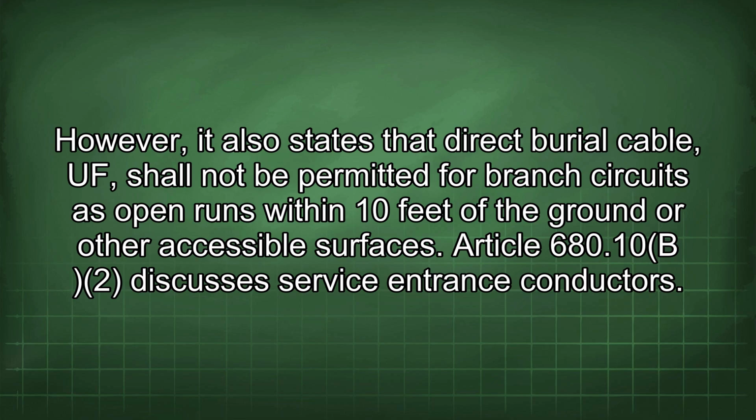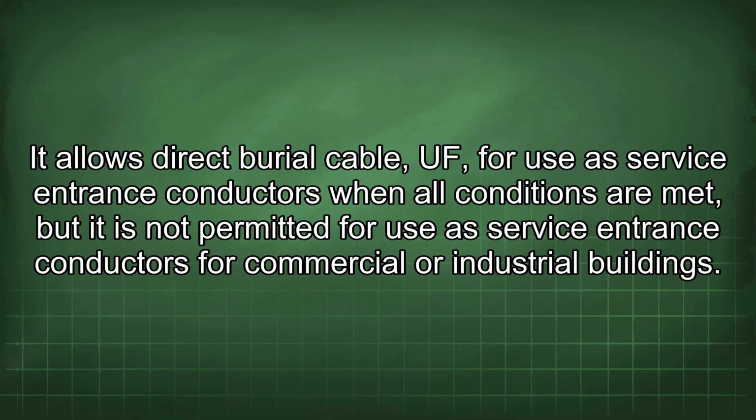Article 680.10(B)(2) discusses service entrance conductors. It allows direct burial cable (UF) for use as service entrance conductors when all conditions are met, but it is not permitted for use as service entrance conductors for commercial or industrial buildings.